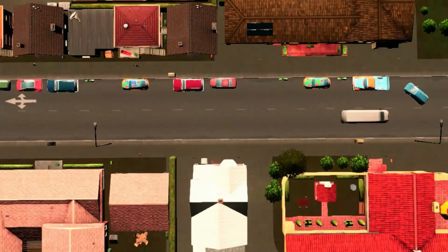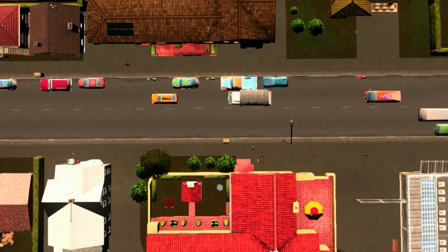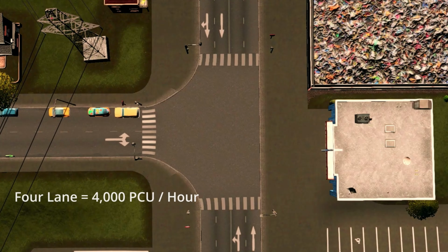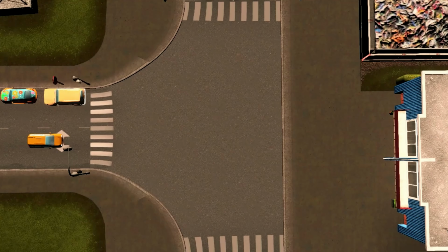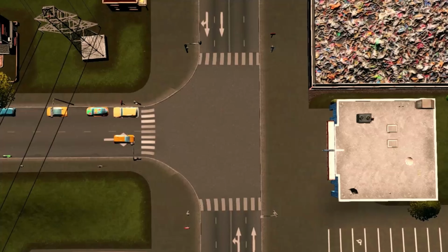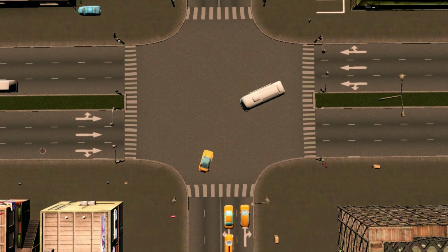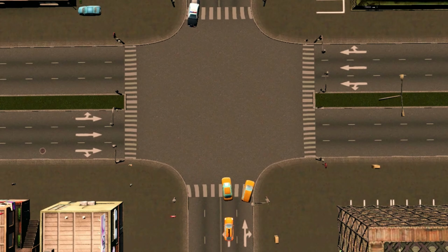For example, if projected peak hour traffic is around 4,000 passenger car units per hour, then a two-lane highway may become insufficient. In such situations, engineers may recommend four-laning to maintain safe traffic flow and acceptable level of service. Similarly, when traffic continues increasing, the highway may later expand into 6 lanes or even 8 lanes. This is why many modern expressways reserve additional land for future widening.